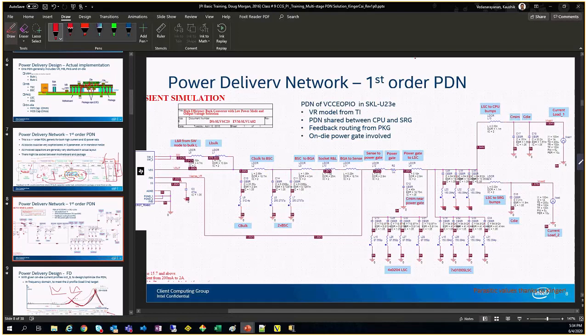As I said, we take a specific RC model, which we generate from a tool and use in SPICE, because we want a very realistic interpretation of what a cap is actually used in the circuit, on the actual board. Intel doesn't rely on vendor models like Murata; instead we generate our own models. We have a team which does the job. So if you look here, can you see the notepad screen now?